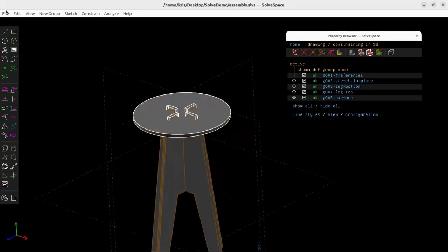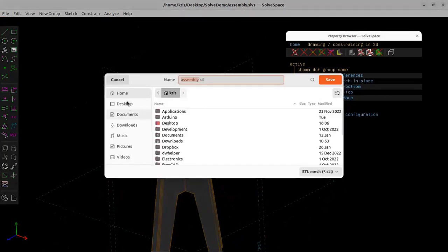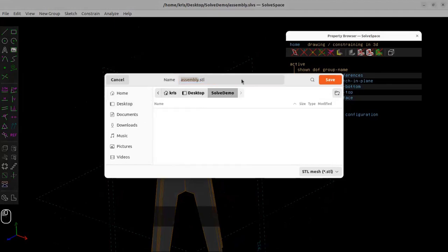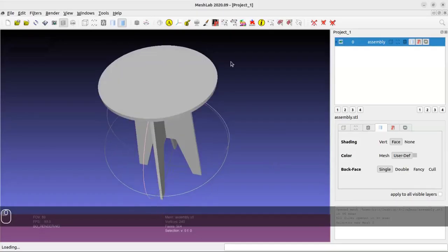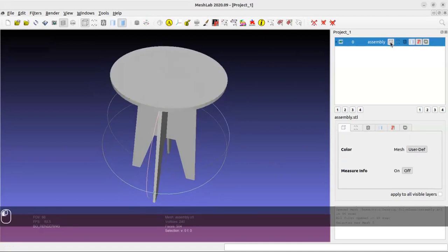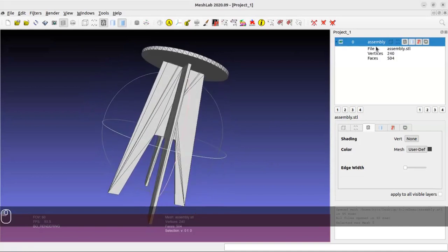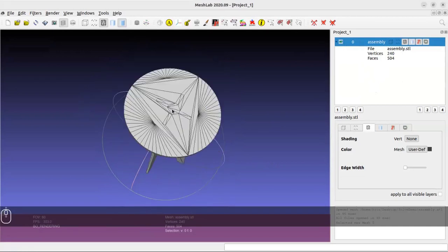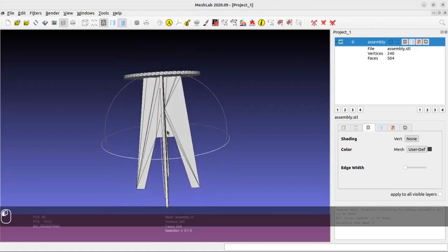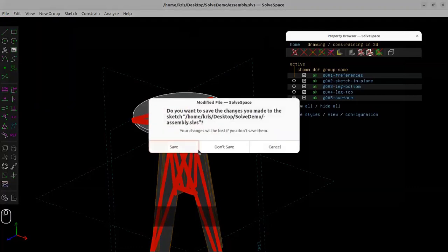So from here, you can export that as a triangle mesh, for example, as an STL file, OBJ file, no problem, or VRML file. Yeah, so probably because it consists of several objects, there might be some problems. It just dumped all the vertices in one file. So maybe a smarter way would be just to export each of the objects separately as 3D files. You can do that. So you can close and open.